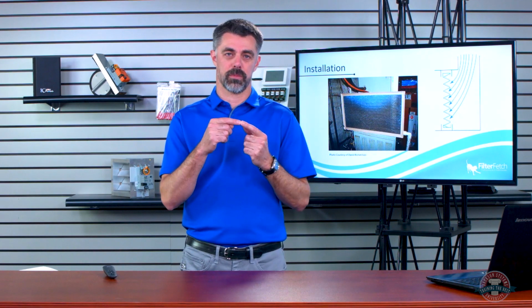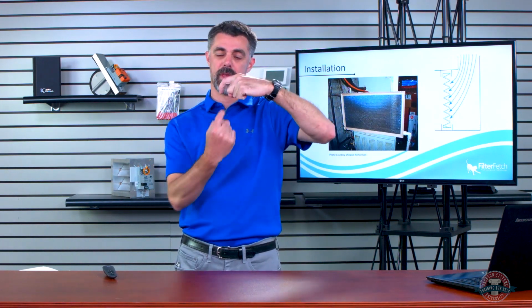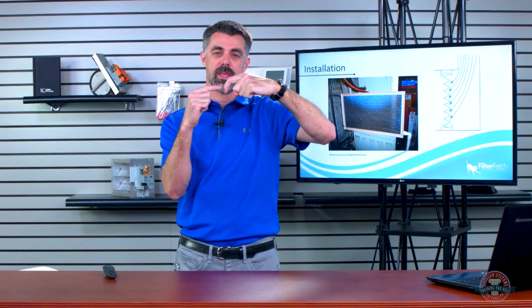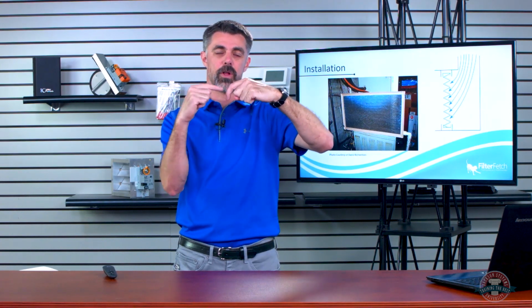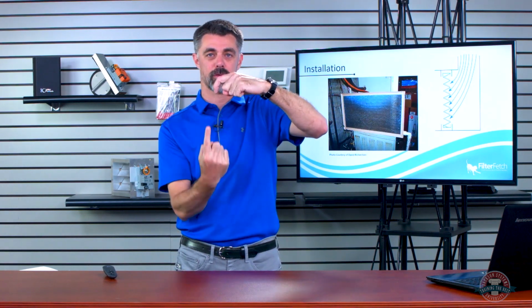It did. Got another one here. When you were measuring negative and positive pressure, Ricardo wants to know how far should those test probes be away across the filter media? Well, you want them fairly close, but you need to have them in some clean air. Because we're using static pressure probes, right? They look like a little hook, and they have holes in the sides of them. And if we get the air pushing in on those sides, it gives us a false pressure reading because we get velocity pressure. We really want that air flowing straight at it or straight across it this way, either direction.